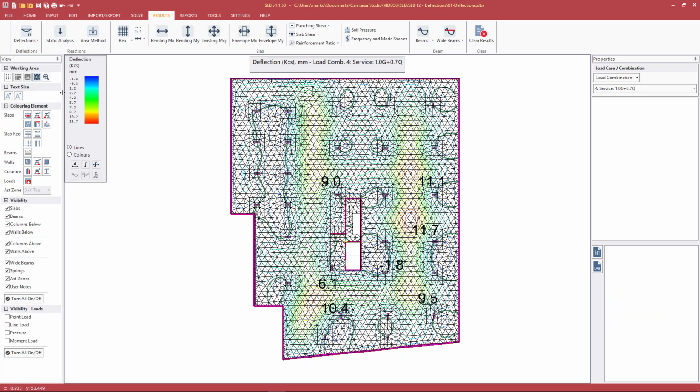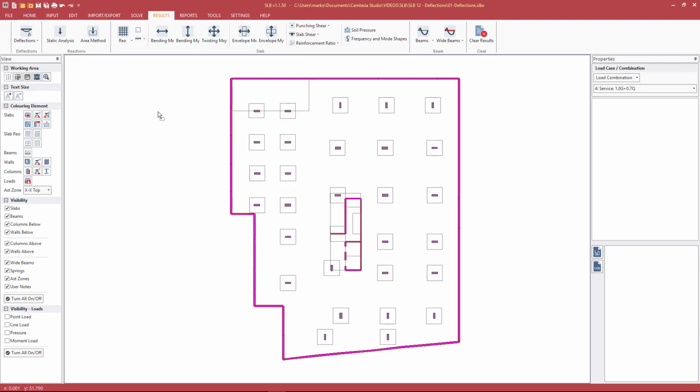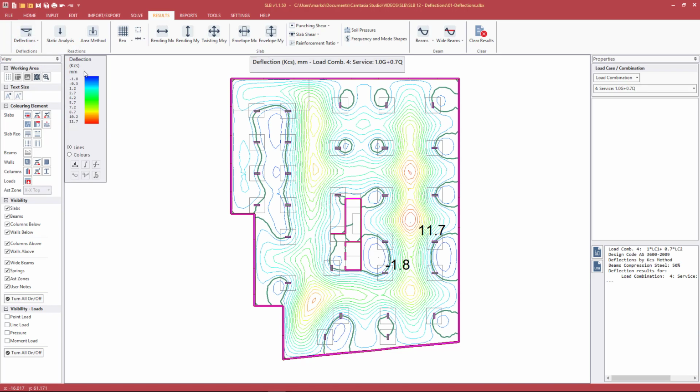Escape to redraw, showing the long-term deflection results again. Clicking displays the results. Another way we can display the results is clicking, dragging and releasing, and the program will show the largest deflection in the area that we just highlighted. So again, here.